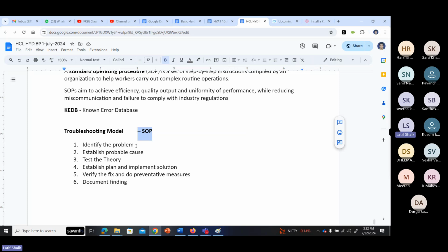Petrol may not be there, the ignition may be damaged, or a neutral lock may have happened when you changed gears and the clutch gear was damaged. We don't know exactly why it stopped, but there can be probable causes. You have to check each and everything so that you understand what is causing the issue.